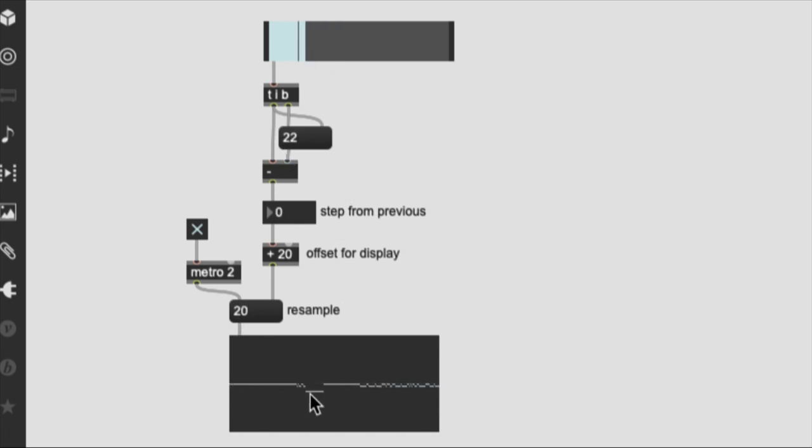So what you would have to do is smooth this signal out. We've looked at smoothing before, and we're going to look at it now as well. But this is what you get, because with a very slow motion, the resolution here is rather weak. So you see I get a lot of zeros, a few -1s. That's the best I can do with this signal with a single differentiator.